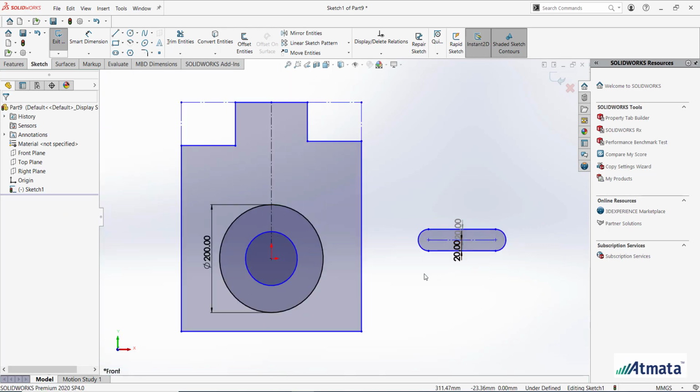So once finished with this, I have another option. Usually what users do is they go and click on the finish sketch on the right side top corner, or you can exit the sketch. To exit your sketch, you have another easy option here, where you can press your D key. Once you press your D key, at the point of your cursor you get an option where you can accept your sketch or finish your sketch, and then you can exit your sketch or cancel your sketch.